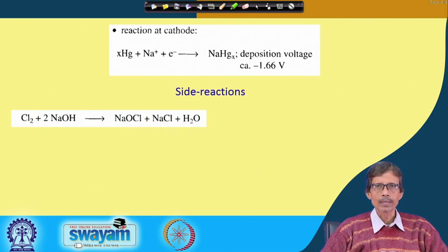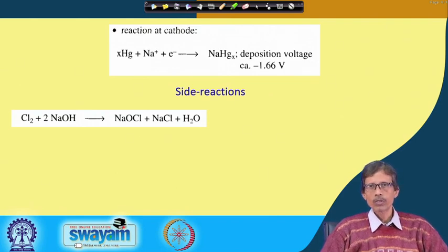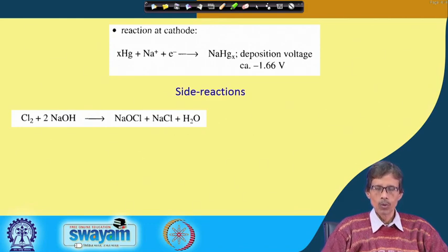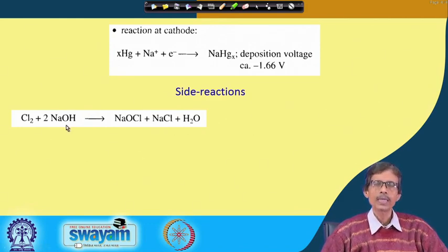But we should also consider some of the side reactions while producing sodium hydroxide. We will be producing sodium hydroxide as well as hydrogen, but some side reactions will destroy our target materials, chlorine as well as sodium hydroxide. During the passage of chlorine leaving your chamber, the chlorine gas can react with the produced sodium hydroxide, forming sodium hypochlorite. We will also discuss afterwards how we can quickly make sodium hypochlorite, which is a very good bleaching reagent and is also very much industrially important.